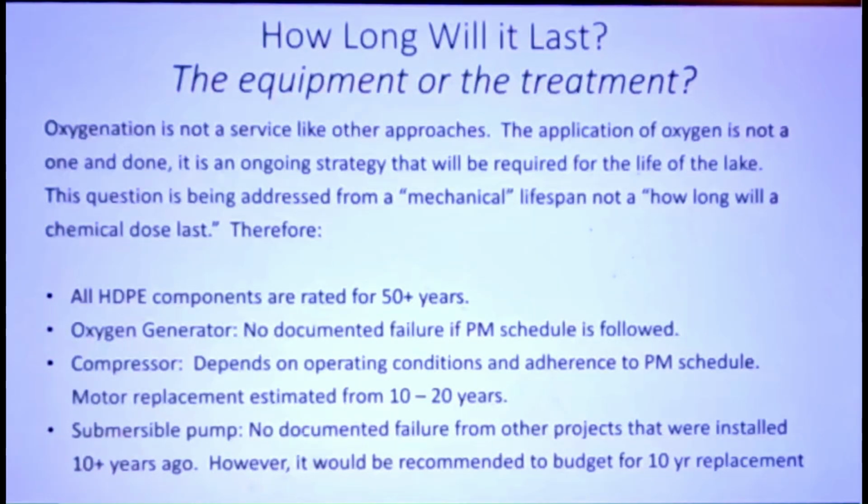With that being said, the piping is written to last 50 years. The oxygen generator, to date, we know of no failures so long as the preventative maintenance is adhered to. If you provide clean, dry air, that sieve bed will last indefinitely. The compressors are mechanical equipment.